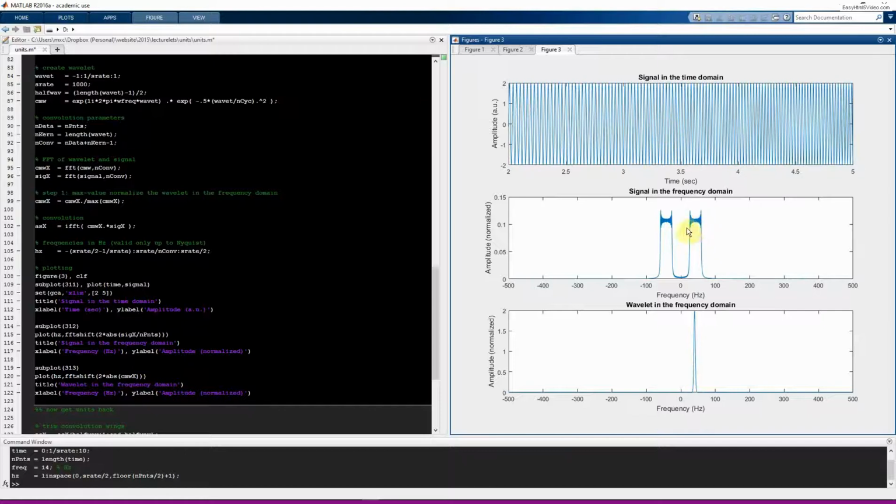When you take the FFT, the amplitudes get split between the positive frequencies and the negative frequencies. For a real valued signal, those mirror each other. Now, when you compute the inverse Fourier transform, all of these get summed on top of each other. The negative frequencies get mirrored over and summed on top of the positive frequencies.